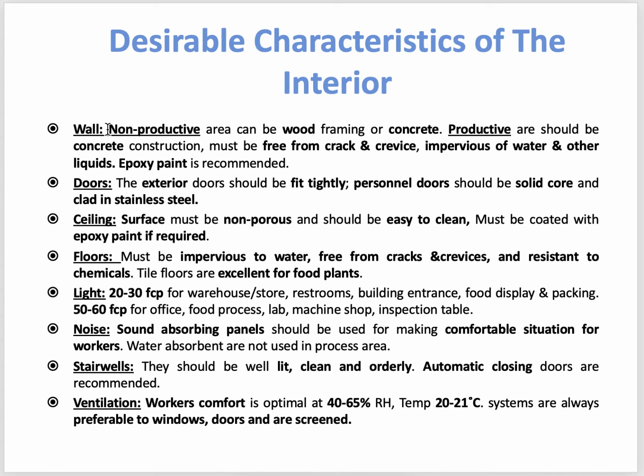For the non-productive area, such as the office or where people do administrative work, the wall can be made of wood or concrete. But the wall of the productive area should be made of concrete, not wood. It must be free from cracks and crevices, and impervious to water and other liquids.